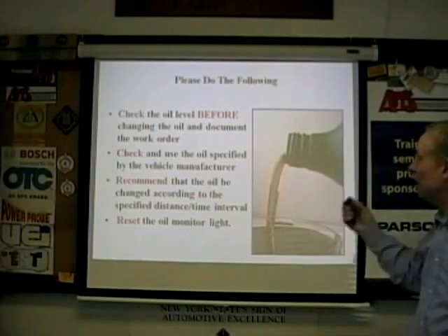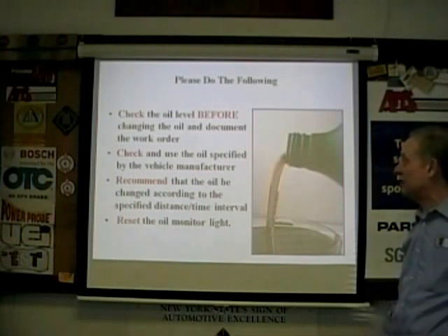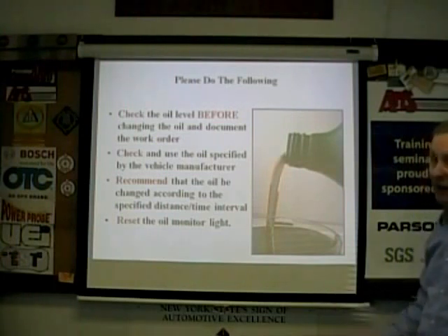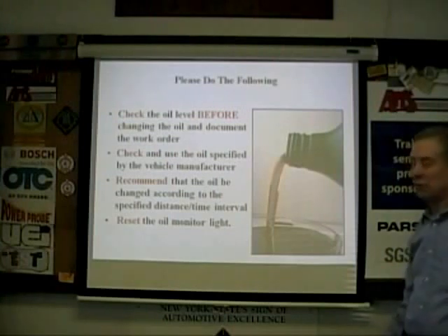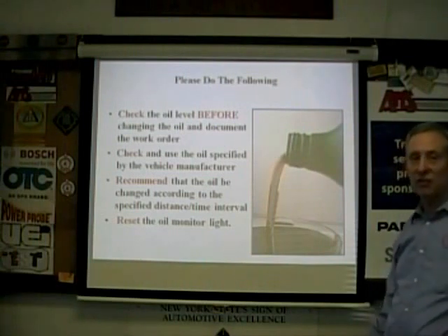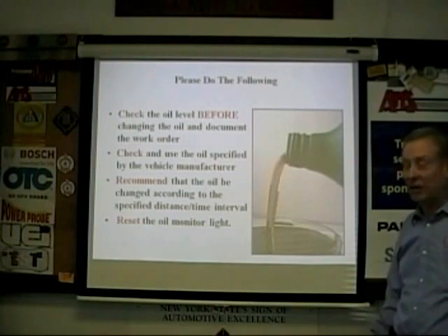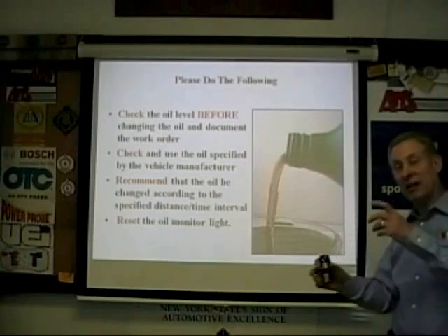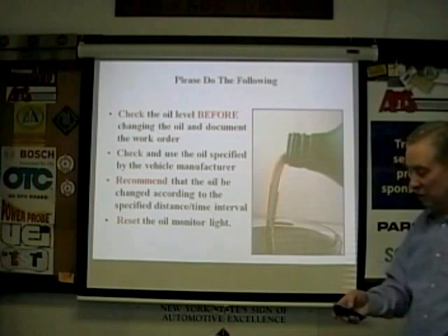All right, do the following. Check the oil level before you change it. Know where you're at, how much it's using. Document it. Check that the oil you're using meets the manufacturer's spec. Read the can. Is there a place, if you have a problem, you could have your oil tested? There are test facilities. They generally send you empty containers and a return envelope, and you take a sample of the oil. My recommendation is warm it up, let some drain, get it from the middle of the stream, and then send it off, and they'll give you a result.